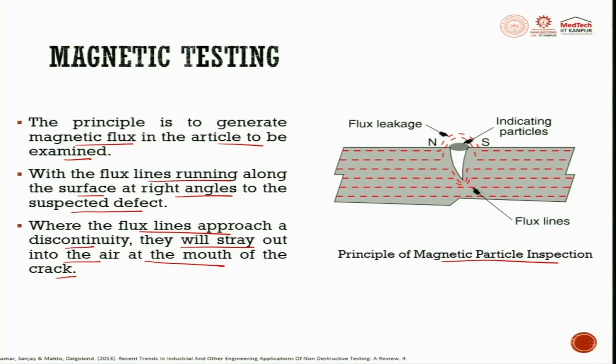For example, in tubular applications, the inspection head is made up of drive and sensor coils and the position transducer. Those are connected by cables to some power source. So this head is placed around the pipe or the tube which is to be inspected, and the drive coil is energized. The location of the signal is sent by the position transducer here. So definitely transducers are used for location of signal.